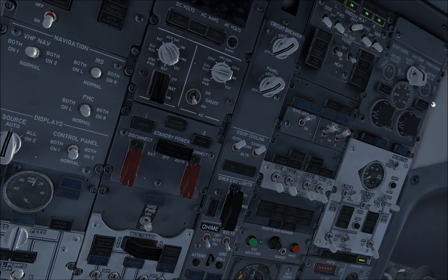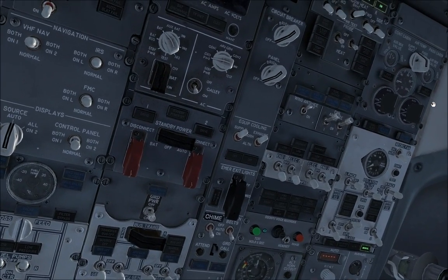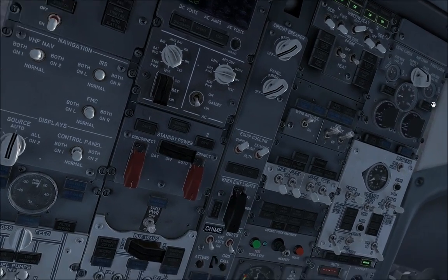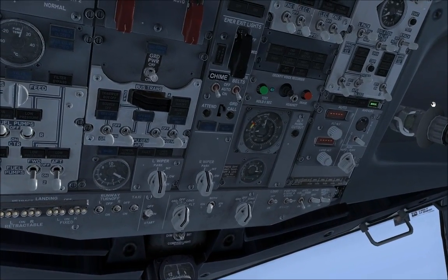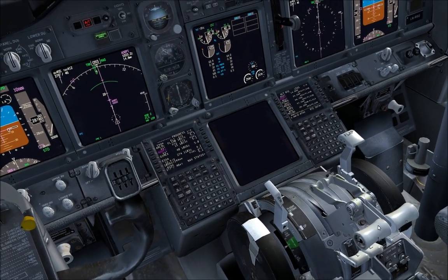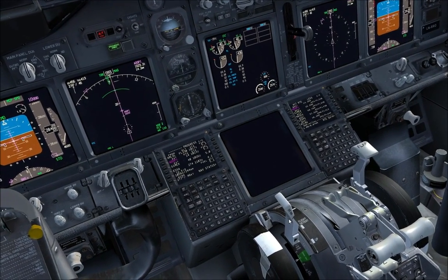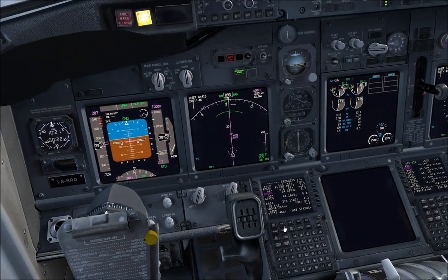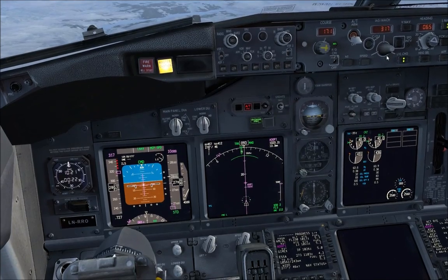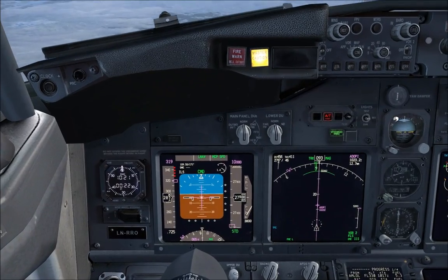Passenger signs on. Without delay, descend to the lowest safe altitude or 10,000 feet, whichever is higher. Engine start switches, both continuous. Thrust levers, both: reduce thrust to minimum or as needed for anti-ice. Speed brake, flight detent. Caution: if structural integrity is in doubt, limit speed as much as possible and avoid high maneuvering loads. Set target speed to MMO, VMO.